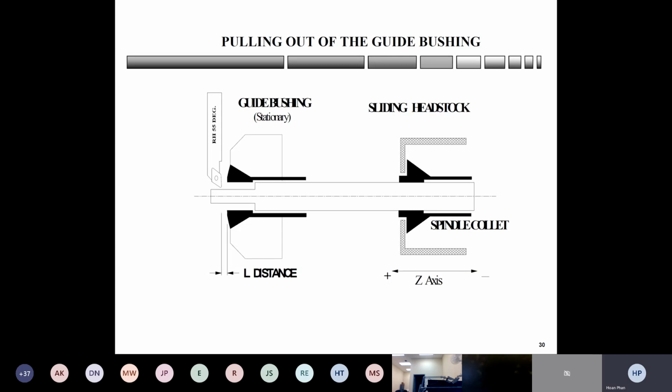I talked earlier about how for the Swiss machine, especially the Cincom machine, we're not going to do roughing and finishing. We're just going to turn only one pass and then finish the OD. The reason is right here. You can see the length inside the guide bushing limits it, and like I said before, it's a little bit over 3/4 inch. You can order it so this length is standing out if you need it.